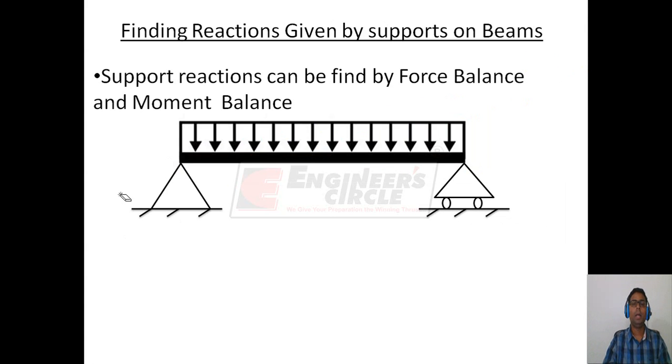The first step in the analysis of the beam is to find the reactions that are given by the supports on beams. Support reactions can be found by force balance and moment balance.